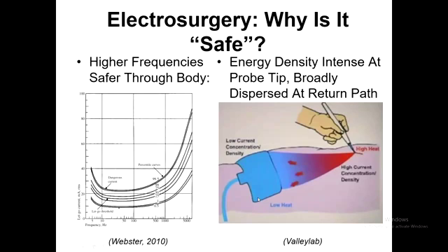This is an example of an electrode that's used at high power, and the major issue with electrosurgery is making sure that the return electrode is across a reasonably wide surface and it's not folded or bent or otherwise unserviceable, because that's what causes the majority of the problems. But if I had been able to show you this thing, it would have been a lot easier to give you a feel for it.